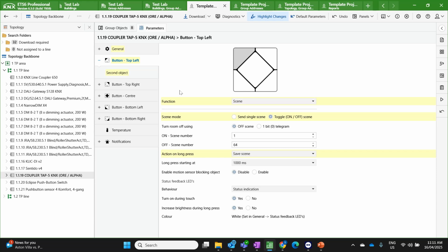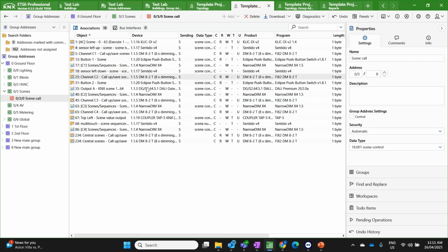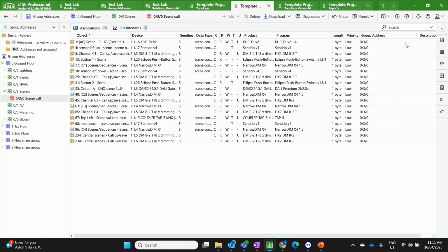This is also very helpful if you're doing a handover or a commissioning and you have a lighting designer in there. If you don't have that scene save function automatically written into the switches or available for the customer because you're a bit worried about it, what you can do is sit here with your ETS, or create a page on your visualization which has this button already done on it.